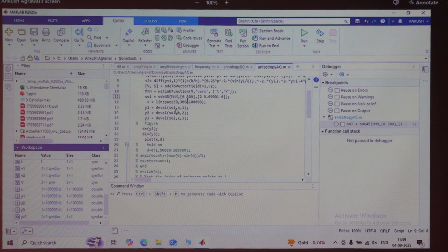Now you can directly consider some different parameter. You are saying that time is from 0 to 300. But I say sub-intervals are also required. Okay. So it will go from 0 to 300 but in very, very small sub-intervals, like 0, 0.5, 1, 1.5, 2, like this. It will not directly go from 0 to 300 but in some intervals. Why? Because for dynamic analysis, capturing the response at the minute points is very, very important. So you have to subdivide the interval.